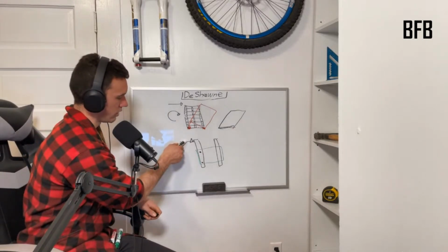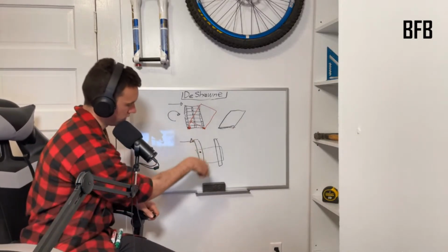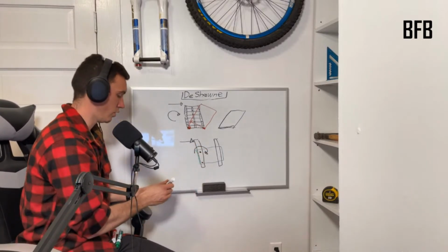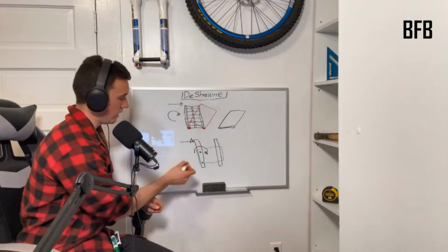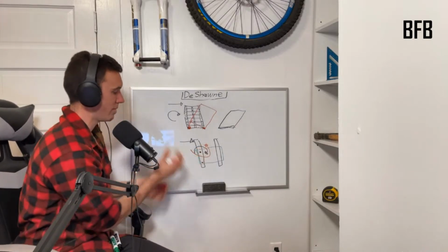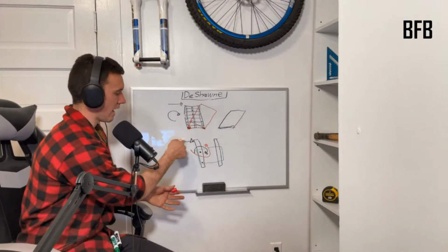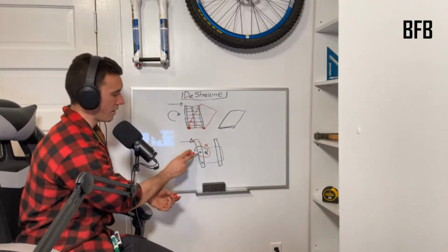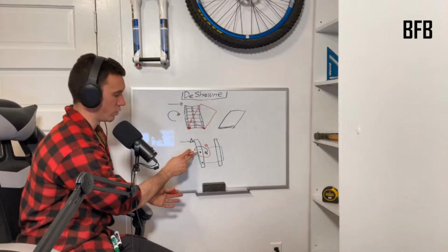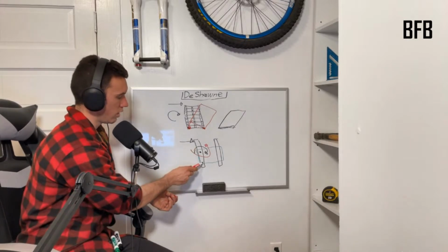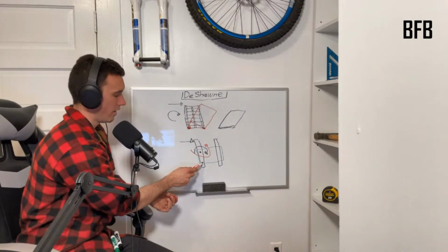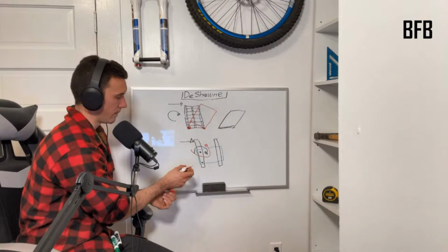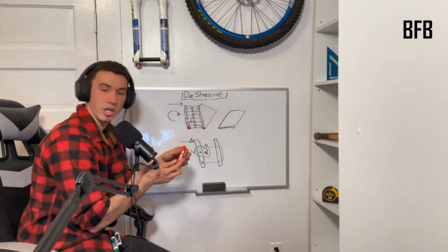So this force is trying to make that member rotate around that point. It's trying to do this, which means for us to make it not move, we need to make it do that. We've got to push back the other way. Well, something outside is pushing it that way, so nothing's helping us up here. And nothing's helping us on the pivot point because we have no friction, and that's just one rotating hinge point. But look, we have a fastener down here. There is a screw that's going to go through the deck plank and then through the joist, and that's going to generate a shear connection, right?